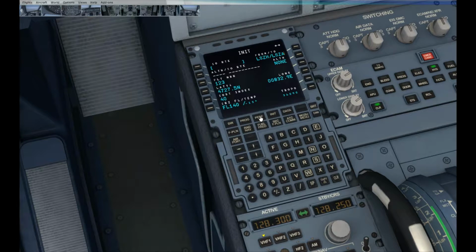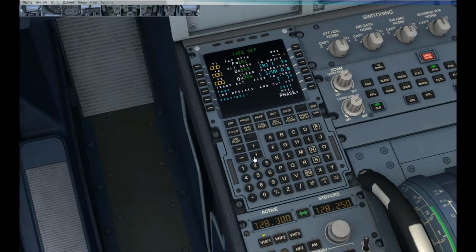Now I need to put in some performance details, so I'm going to select 2 degrees flaps for takeoff. That will give me my rotational speeds, etc. And then we shall look through various phases, and I shall put in the standard air pressure landing 1013, and I will assume a temperature of 8 degrees. Obviously this can be made more realistic if you use real-time weather.